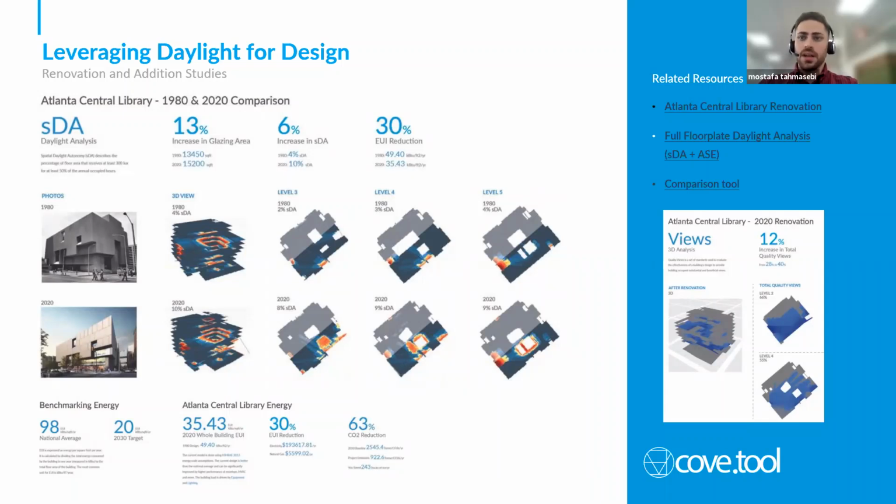So we can see immediately, in this case, for a library, the average nationwide EUI is 98 versus what we have here, which is around 35 to 36 for EUI, which again gives us some information about how using the optimization engine to come up with the right bundle improves the results of renovation and provides us with what we're expecting. In this example, a government project, we have to work with a specific amount of money and we have a limited timeline. Government projects usually require the quickest result and outcome with a limited amount of money.